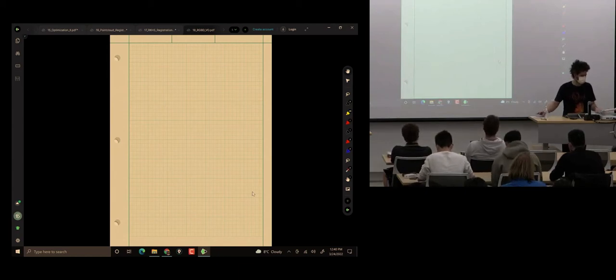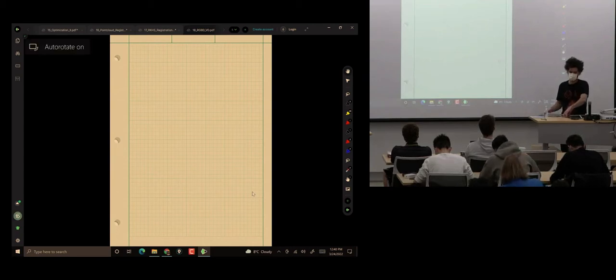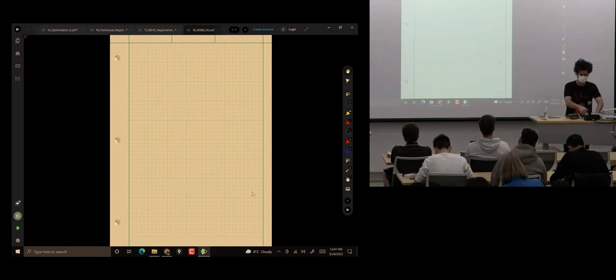The way I want to formulate the problem is using nonlinear least squares. Nonlinear because we will see it ends up being nonlinear. And we'll try to come up with ideas and see how we can formulate a least squares problem that finds this camera pose by aligning two consecutive images. So in some sense, frame-to-frame RGBD registration is similar to point cloud registration. Because we could work with point clouds directly, and we could, in fact, use previous methods that I discussed that integrate color and point cloud.